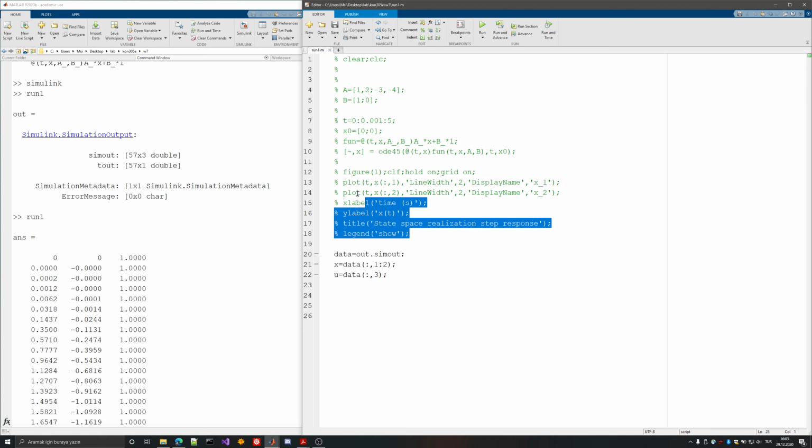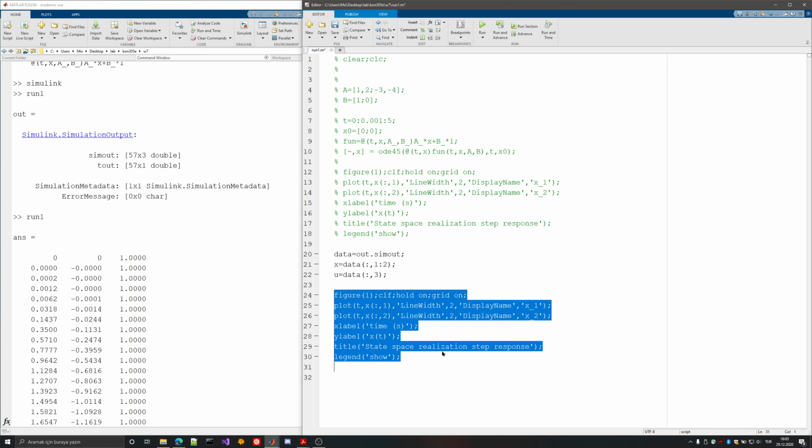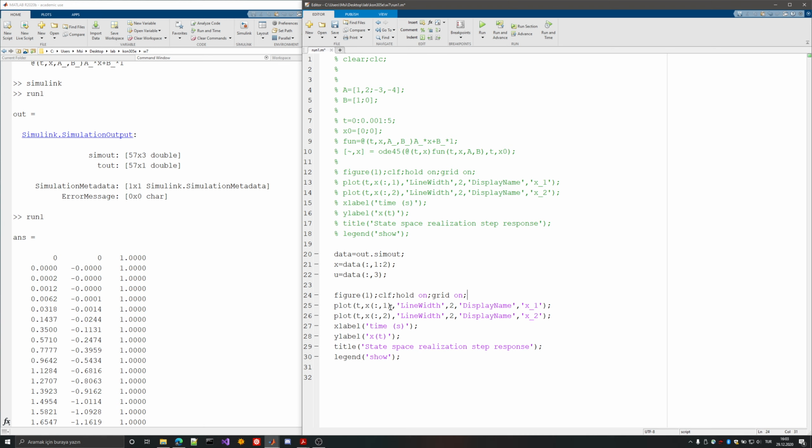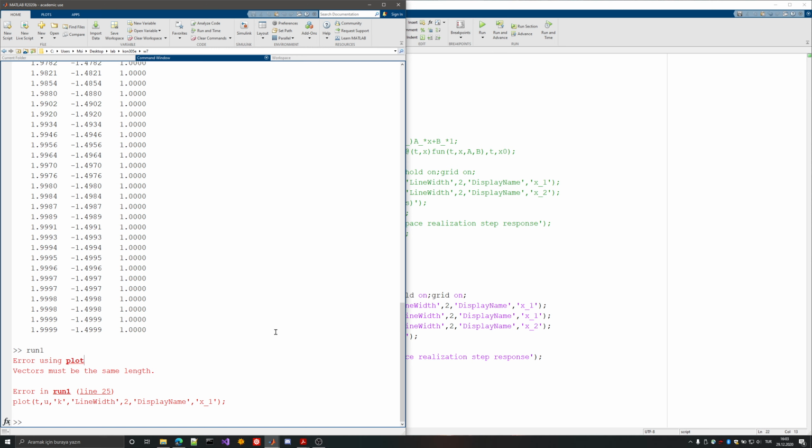And then I can go ahead and use this here instead of my scope or my code. I'm just going to use this data, and I might also add a plot where I have the input reference plotted too. Maybe I will give it a color of black. So that's it. Now if I run this after running the simulation, by the way, I need the time data.